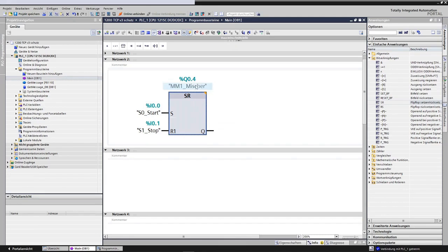In this case, I did not give it any memory space, but said, just store your state in an output. And that is not correct. It works, and it also saves resources. That used to be interesting regarding resource savings. Nowadays, that is no longer an issue. Therefore, one should place a virtual memory here, such as a variable or a fixed address memory, a memory bit, in this position.